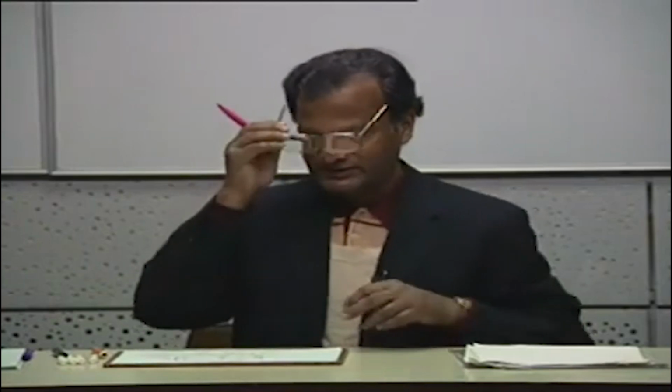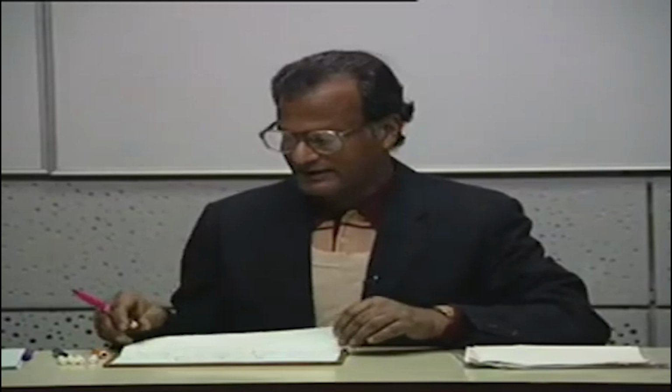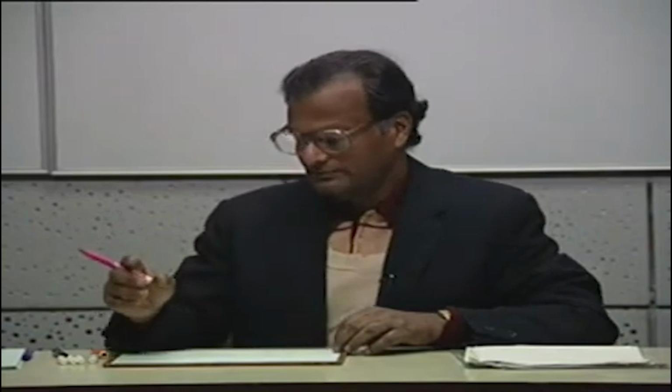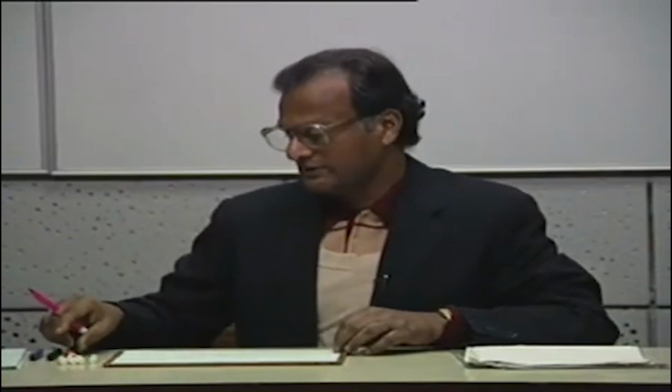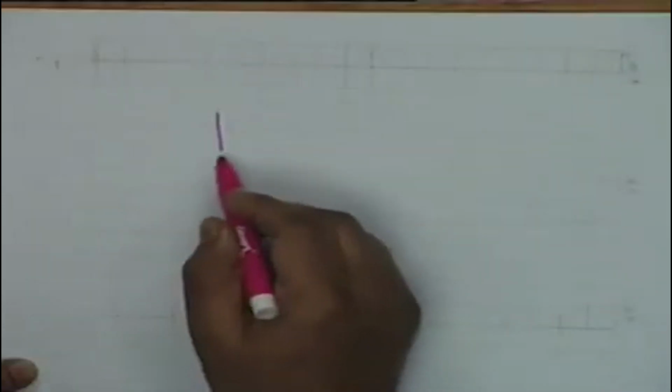Conservation of energy, alright. So KCL and KVL are nothing unique in electrical engineering or in network theory. They are expressions for familiar conservation laws that hold: conservation of charge and conservation of energy. Now let us see how we can use them in analysis of a circuit. We shall go through a series of examples and illustrate how KCL and KVL are useful in solving quite complicated circuits.